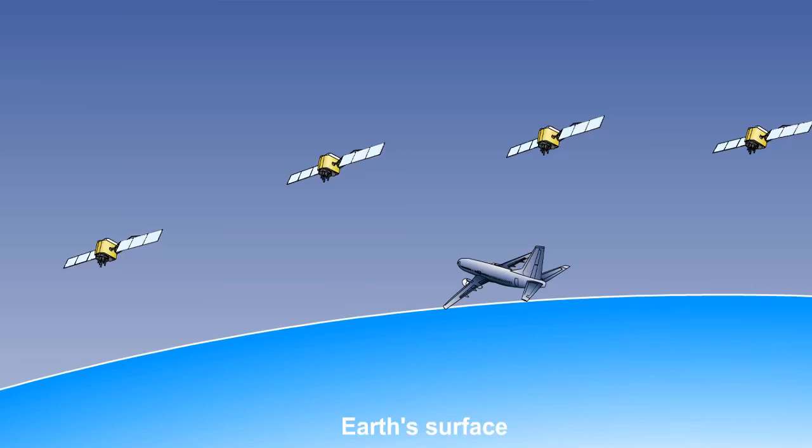All GPS errors are stated at the 95% probability level. That is, 19 out of 20 times, the accuracy will be within the stated limits. Of course, it also means that once out of 20 times, the limit will be exceeded.